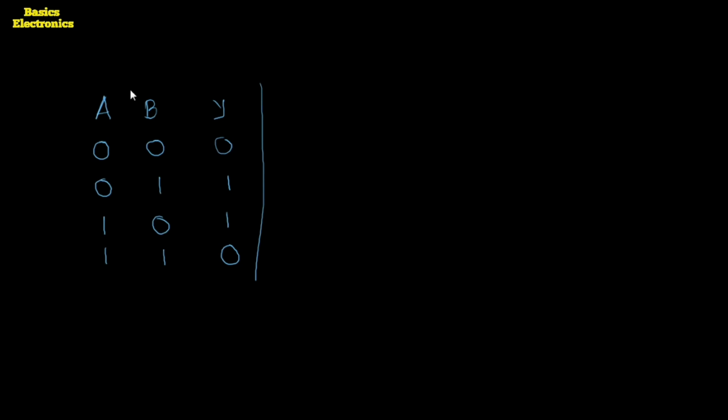This truth table has the two inputs A and B, meaning the multiplexer we require to use is the 4:1 multiplexer again. Why a 4:1 multiplexer? Because a 4:1 multiplexer has two select lines, and here again there are two input variables.